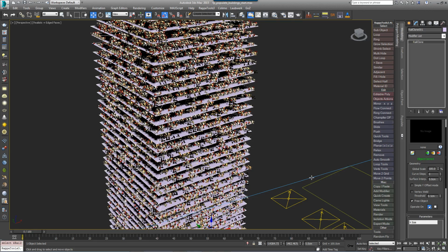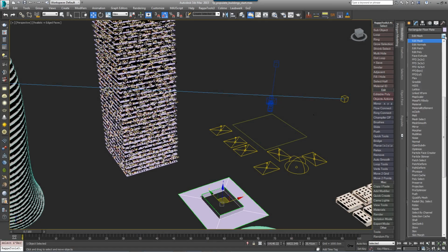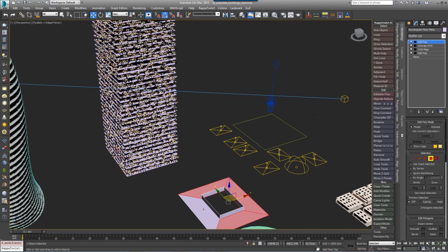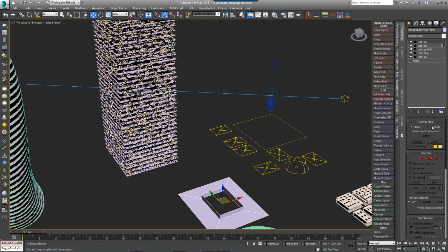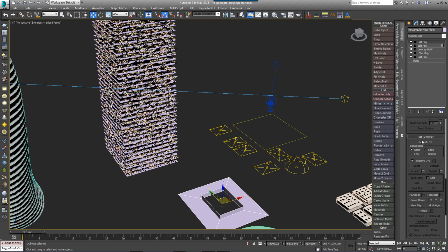As with the UVW modifier, one scene unit equals one UV tile. By using these values, we're ensuring that the randomization keeps the UVs within the white area of the map that we created earlier in this tutorial. You should now see that the distribution is randomized on each floor. When preventing objects from penetrating the facade, we're still using UV mode, so the best way to control the scatter is using the distribution map as we described earlier.